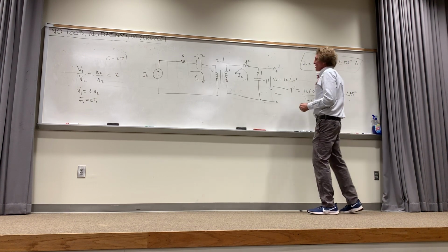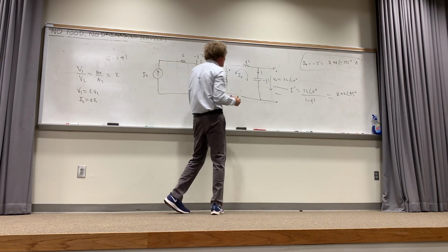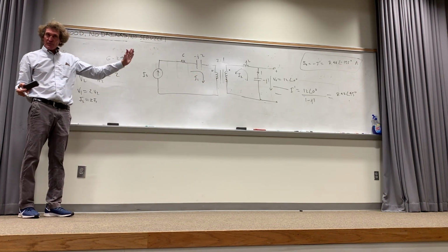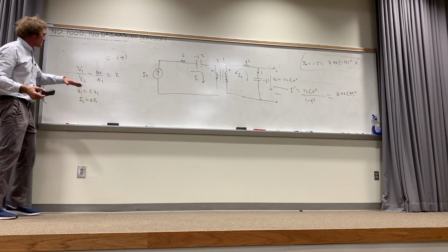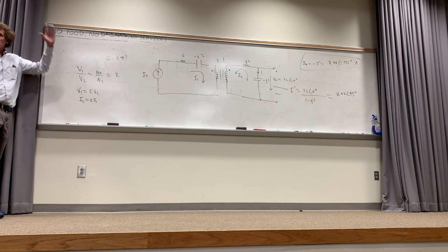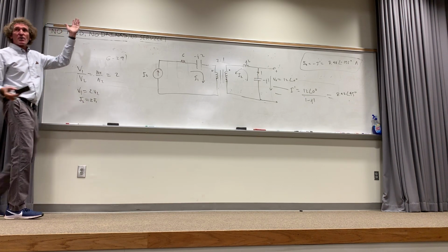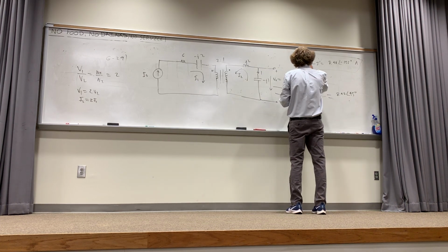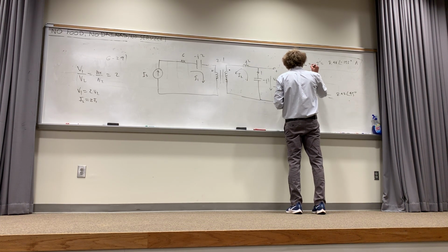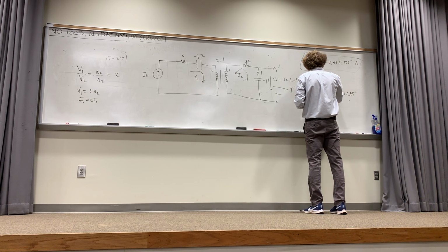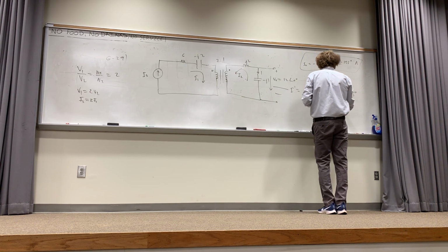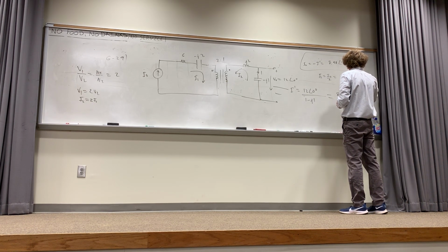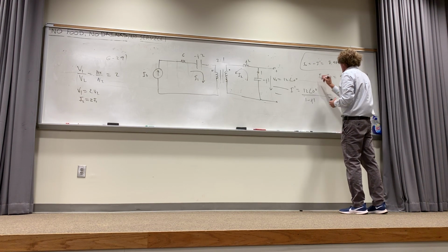That's I2. I1 is simply I2 divided by 2. Do you all see that, class? I1 is going to be just half that, based on this equation right here. Correct, everyone? Are you with me? Now, his answer's wrong in the book. I'm almost positive of it. So if you take this I2 right here, I'll talk to him afterwards, and say that I1 is simply I2 over 2, that's going to be 8.48 over 2, which is 4.24 at an angle of minus 135 degrees, amps. And that would be I1.